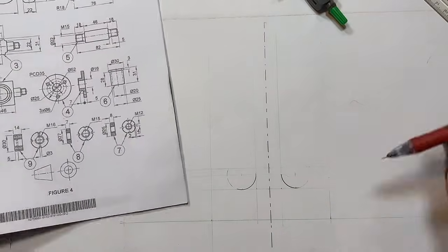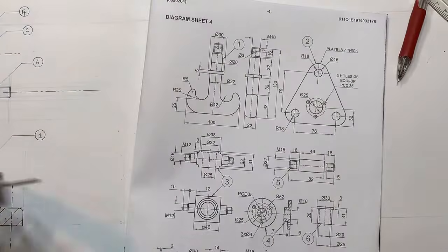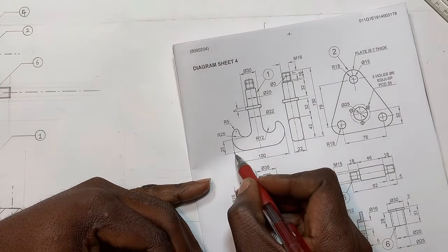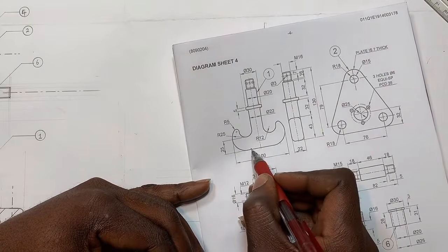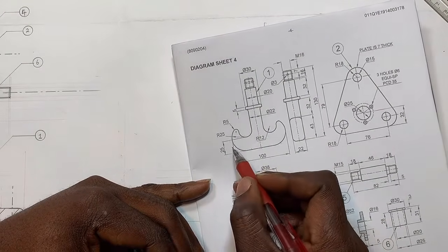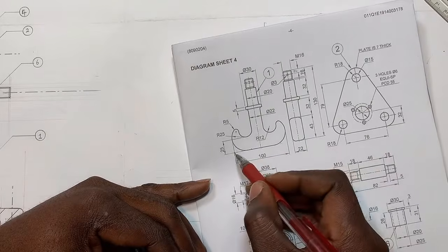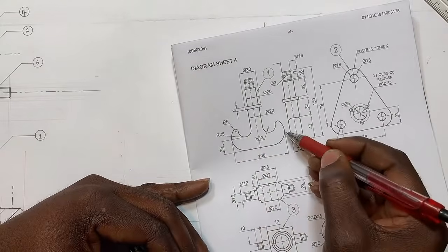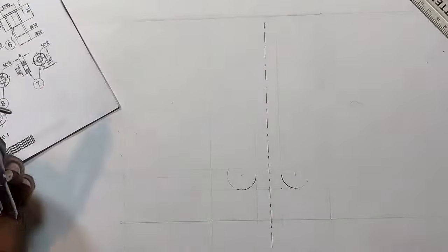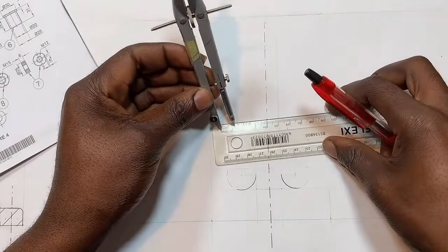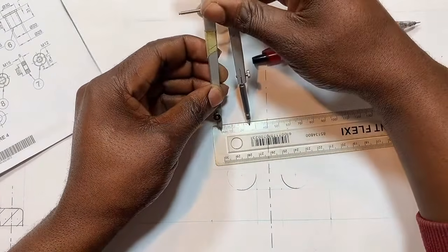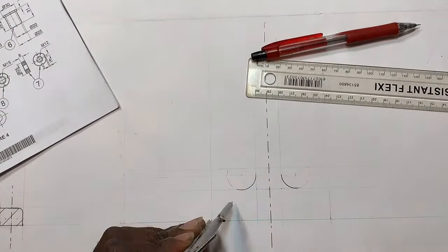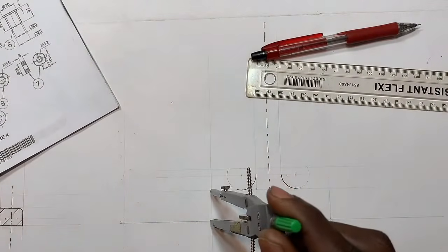So to get that, simple, straightforward again. I have to get the sharp corner, which is that one. So from this corner coming this side, I'm going to record how much? 25, going up 25 again, so that I open my drawing compass, place it somewhere here, and strike this arc. So radius 25 to get this one, radius 25 to get that one. You get it? So I'll simply open it to 25, which is this one. So now I come to this side, I place mark here and mark right there.